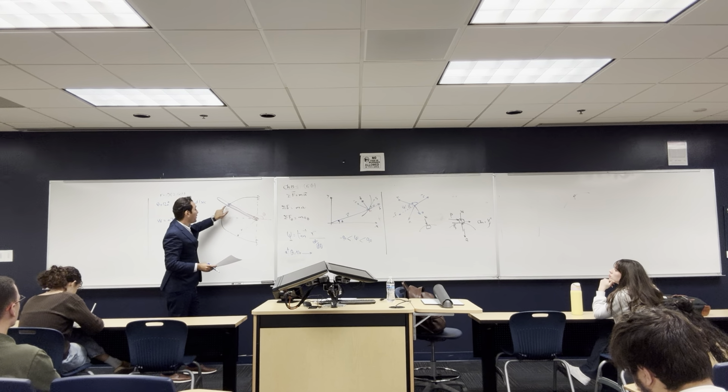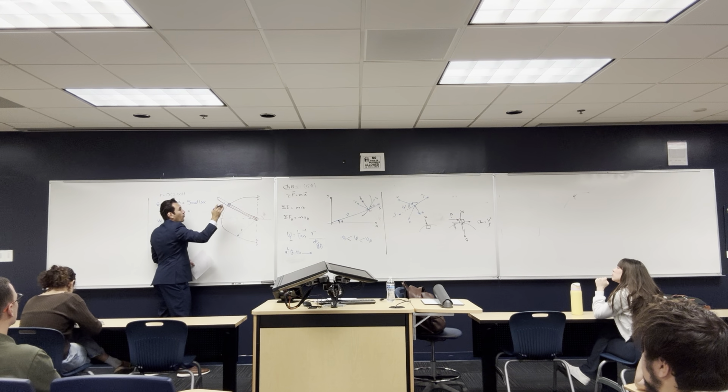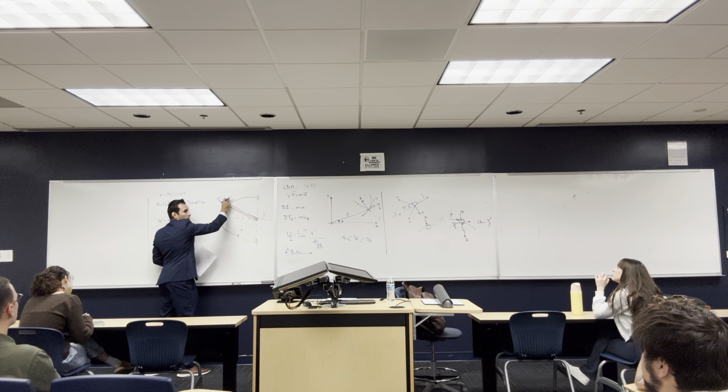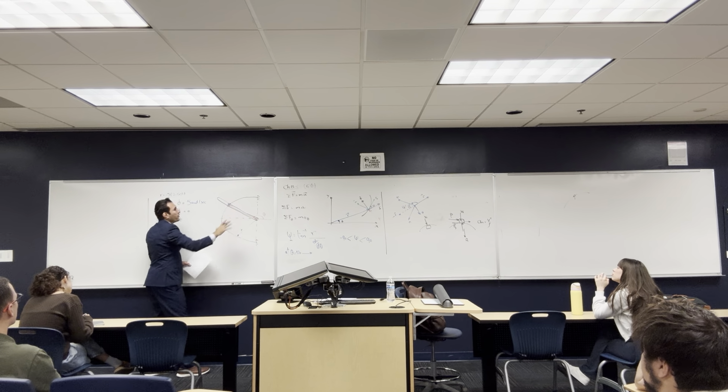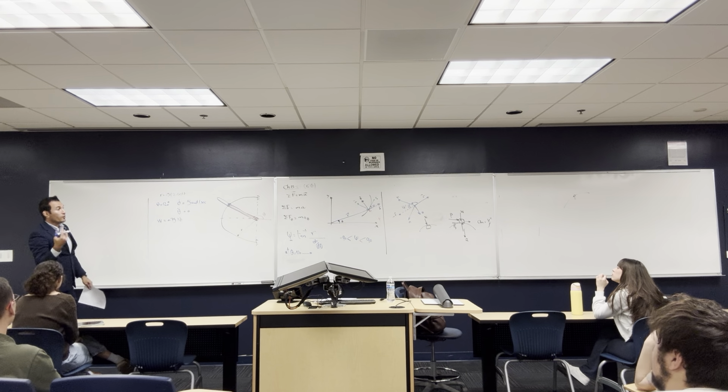Like if you push this arm, what is the value of the weight? Like if you have a weight here, this weight is going to make this part move down. I want you to find out what is the force being used on this arm by this weight, and what is the normal force from the surface on the arm. The thing is, as I told you, to solve any problem like this, you have to draw a free body diagram and you get points for that. If you didn't, you're going to lose points.